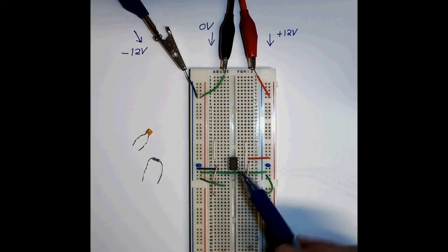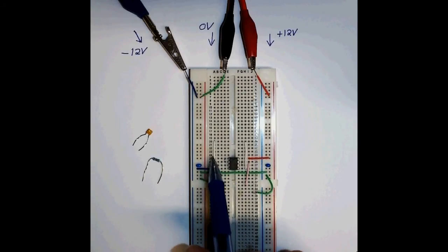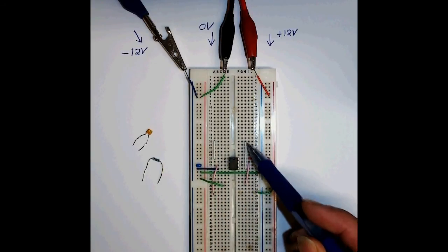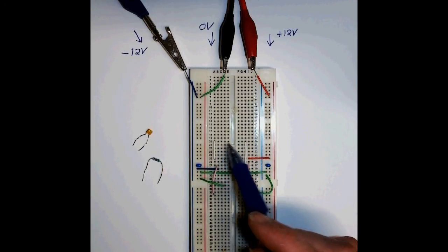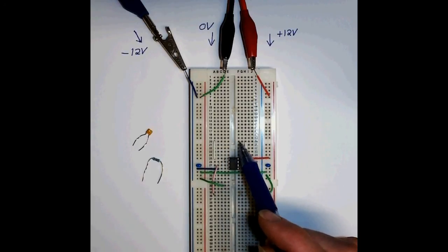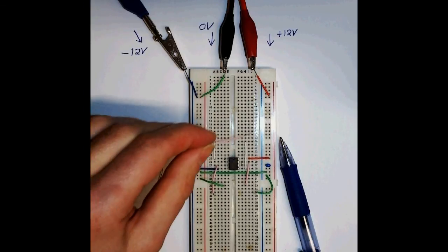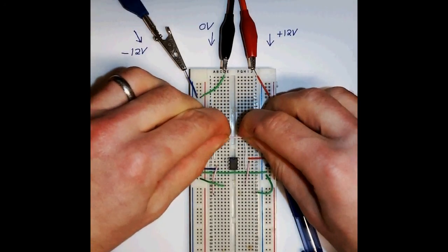Then, the output from this stage of the op-amp, which I'm going to use as my buffer from the VAM output, drives this white wire up to here. The input to the second stage comes from this white wire from up here. So our test circuit we should put between here and here. And to do calibrations, that means just putting a wire between there and there. I can use this pink wire to put that connection in, between there and there. Boom, boom.